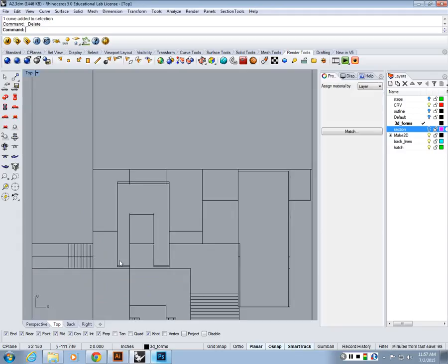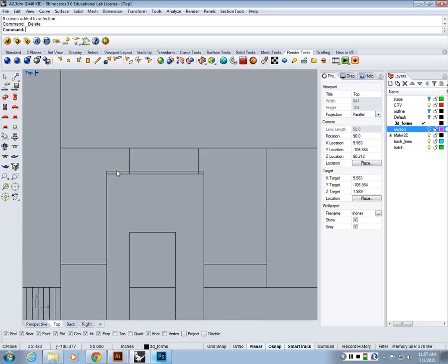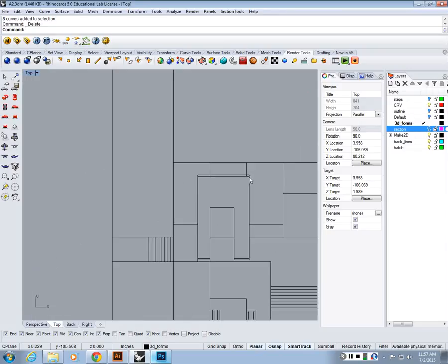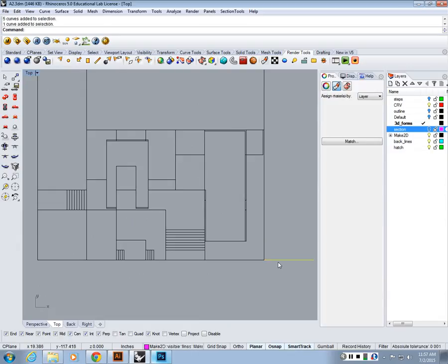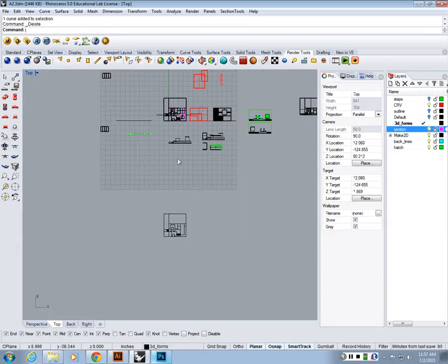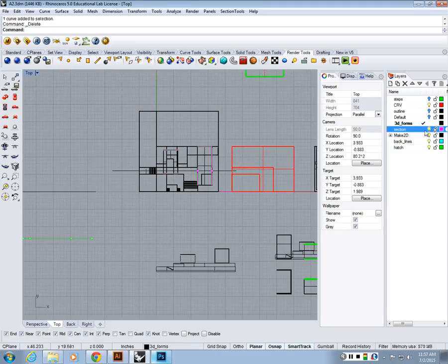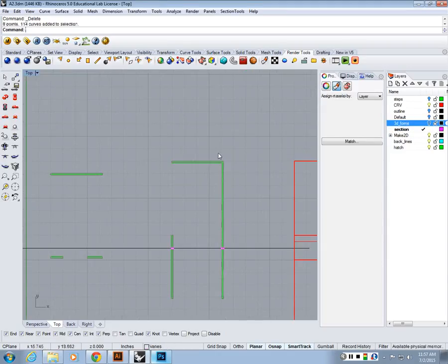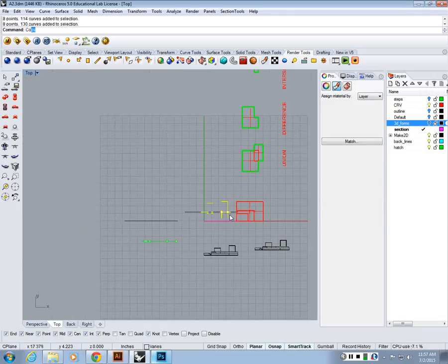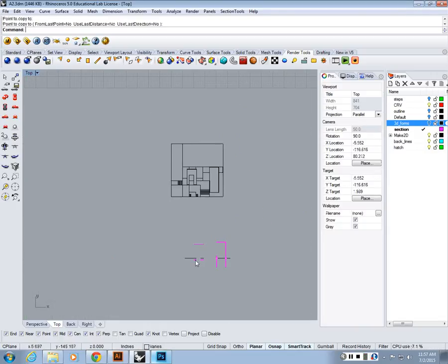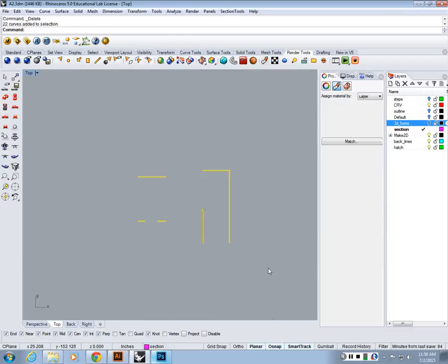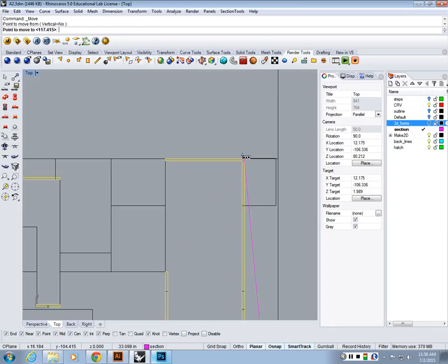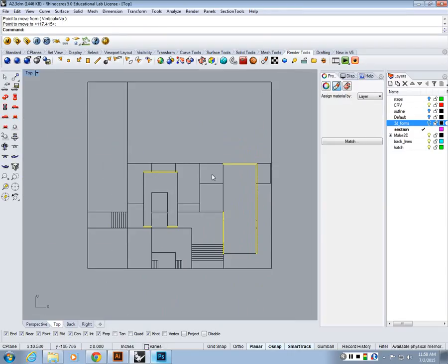I mean, technically, if you know the elements that are cut, you could just fill these up in Illustrator as well. You don't have to deal with the Poché, right? Like I'm seeing all these double lines, so it might be even easier. But if you want to use them more precisely, you can bring them in. So these are my section walls. I think these are already cleaned up, so this is already good to go. I'll just bring this guy here. So these walls are going to be pocheed. These surfaces are going to be cleaned up.